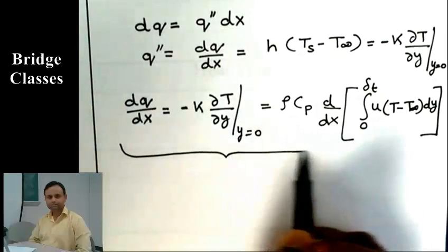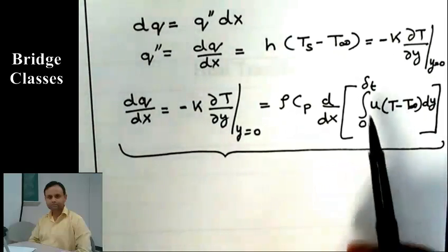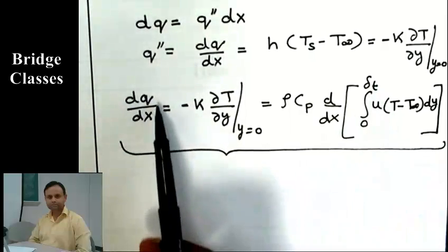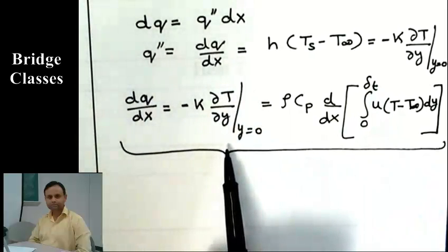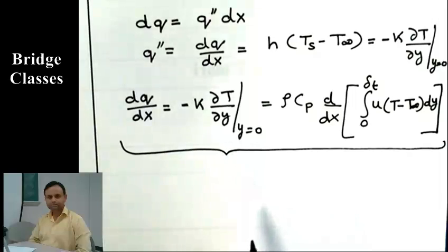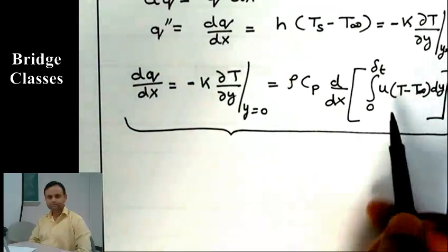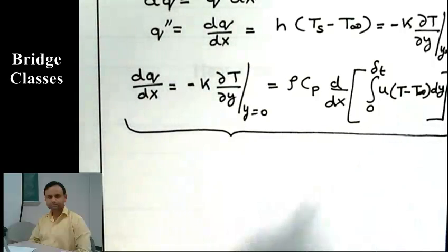This is the expression we were looking for. This will give us the value of delta T, and we can use that to get the Nusselt number or convection coefficient. It is analogous to what we did with the momentum equation. Now the approximation: we assume a profile for temperature.